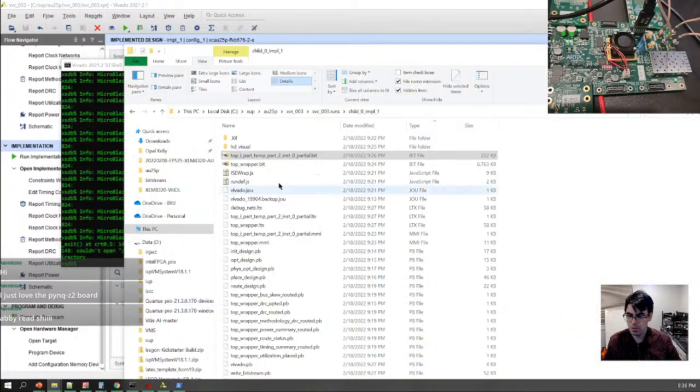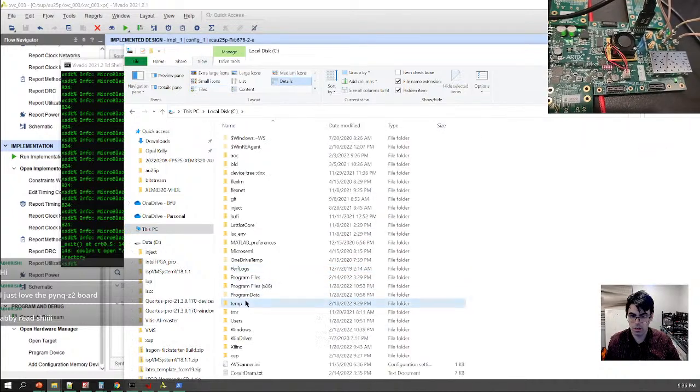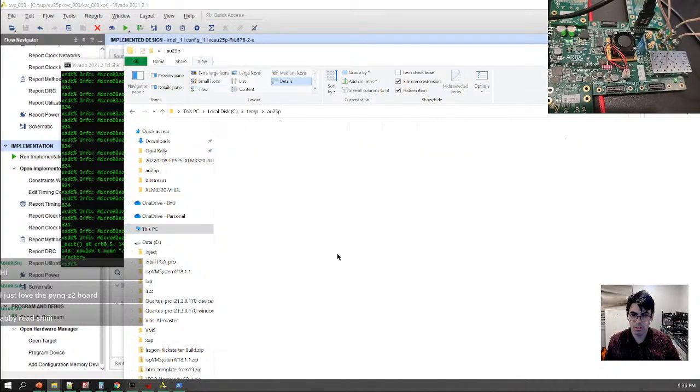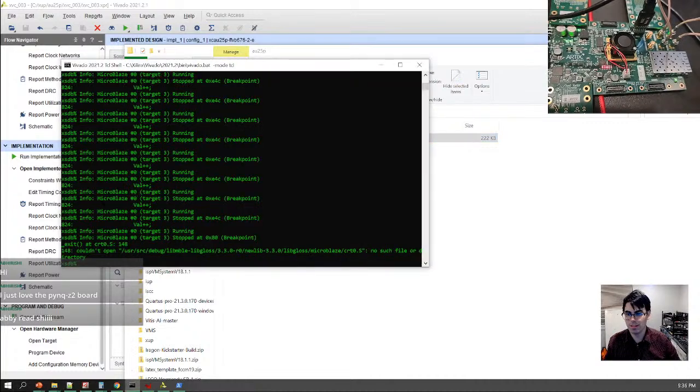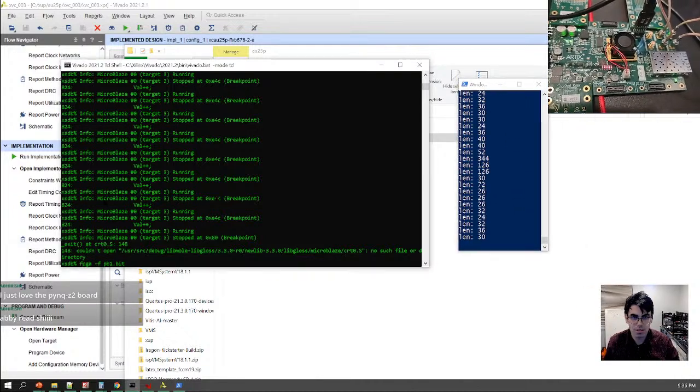We're going to take our partial bit, go to our temp folder here, and rename it partial bit 1, pb1. Then we're going to run fpga-f pb1.bit. I want to see what happens to this guy when we do this.